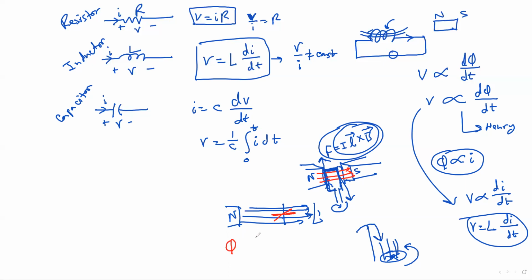So we denote the number of flux lines by phi, right? So this expression of phi is varying while the coil is rotating, and the expression should be something like this, if omega is the frequency of rotation of the coil. So the variation suggests a cosine or sinusoidal idea, right? And if you do some calculations, for example, the overall full face area, say, is A naught, then at any moment the area is A naught cos omega t.